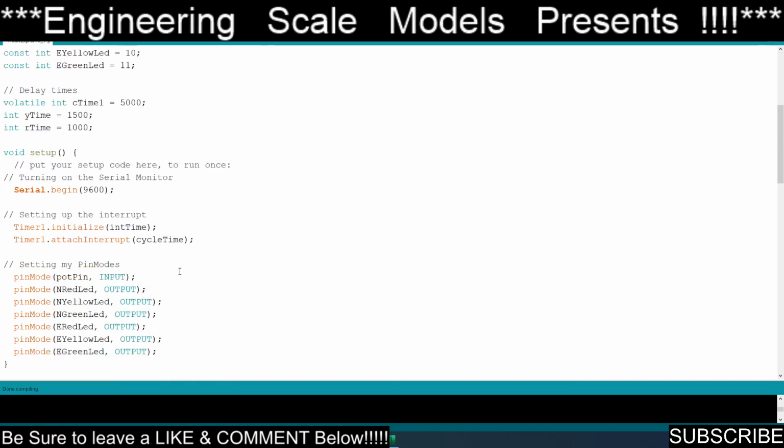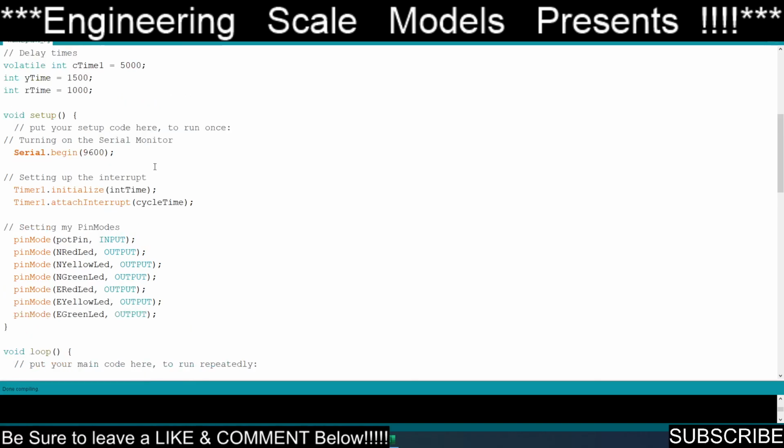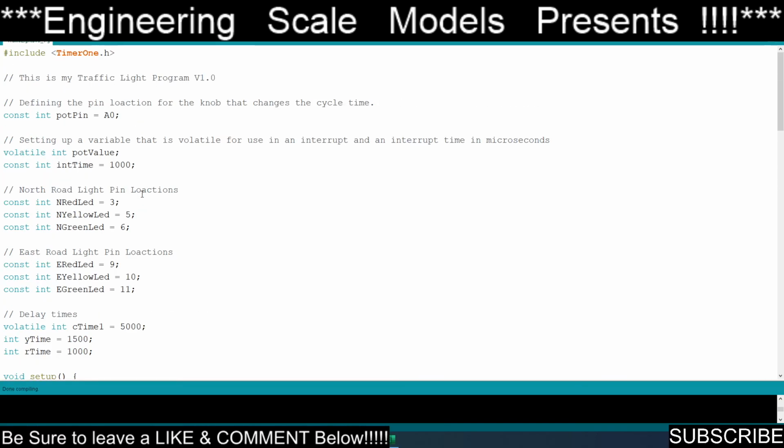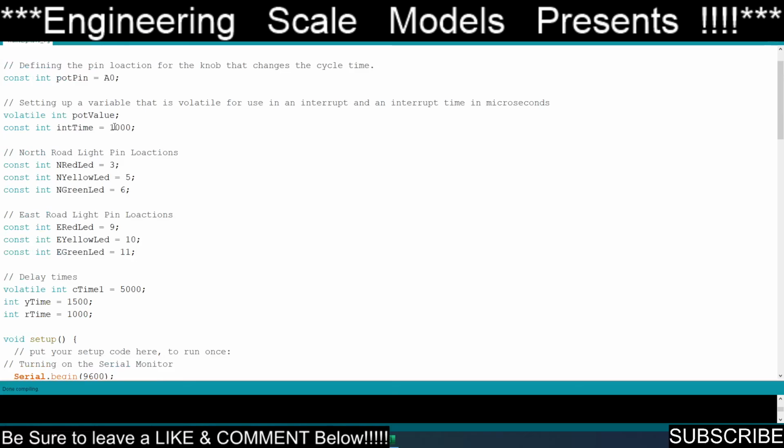Now I come down here to the void setup, and this is where I need to set up the interrupt. You do Timer1 initialize, and then you do your interrupt time, in microseconds. I'm doing 1,000 microseconds, so I'm doing it every millisecond. It is interrupting the program to check the value of the potentiometer. Because that's all I'm doing, I could change that to another 0 in there, and I shouldn't have any issues.